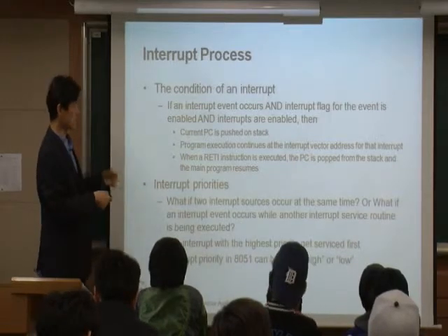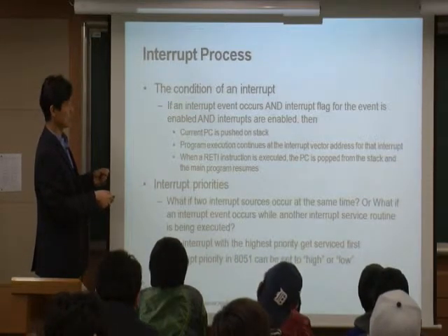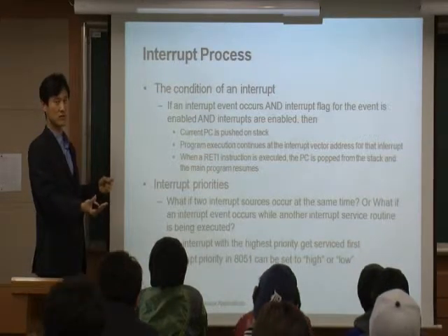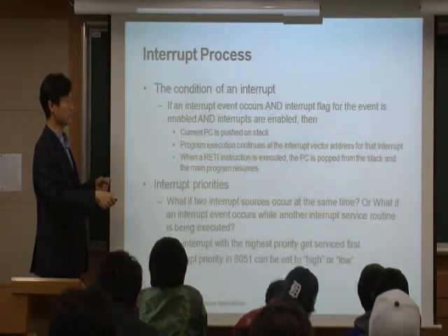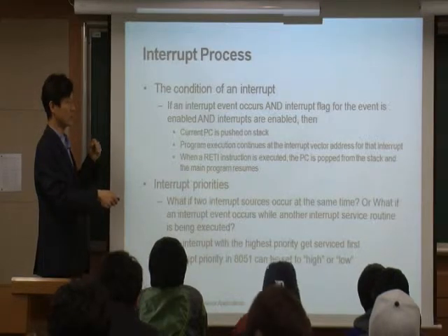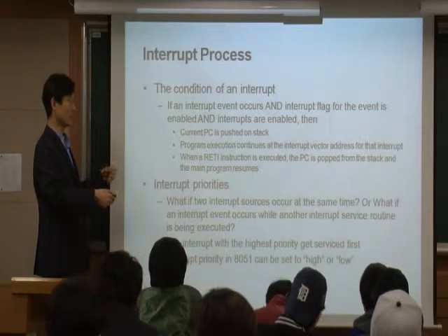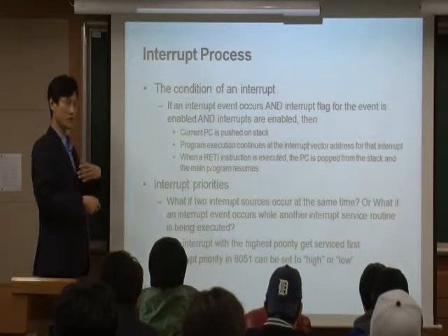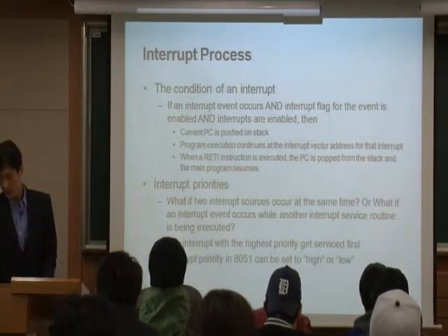I'll tell you about this in the next slide. And whenever you see the RETI instruction at the end of your interrupt service routine, you pop the program counter from the stack and restore it, and then you come back, and the main program will resume.